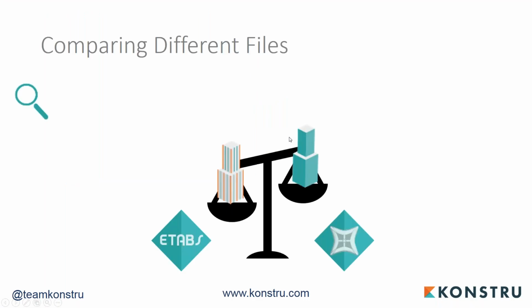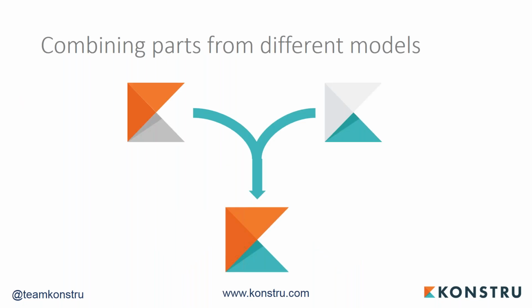And so we only have 5 minutes left. But a few other things that I just wanted to mention here is that one thing that you can do with Konstru is also uploading 2 different files that have never been synchronized before. So unlike today, where we created an ETABS model from an existing Revit model, what if you had 2 separately created models? You can actually upload them, and you can compare differences, and you can again create change reports from those. And then the other thing is also you can combine parts from different models.